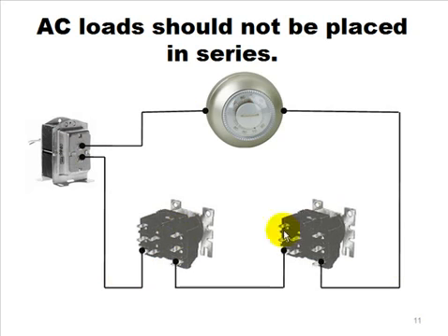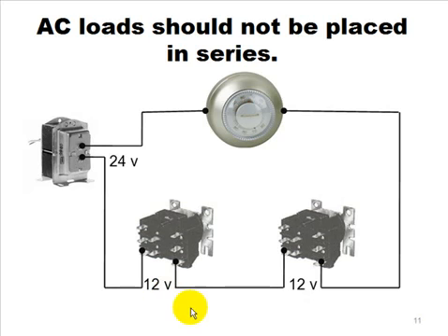What I don't have is the proper voltage, because when I close the thermostat, these 2 are going to sit there and hum because they're both the same. They both have the same resistance. I have 24 volts available. I put them in series, and the result of that is each of them sees half of that voltage. So this 24 volt coil is never going to pull in with 12 volts. Any more than a 120 volt motor will run on 60 volts. It'll attempt to. It'll make a lot of smoke and a lot of humming, but it ain't going to turn.